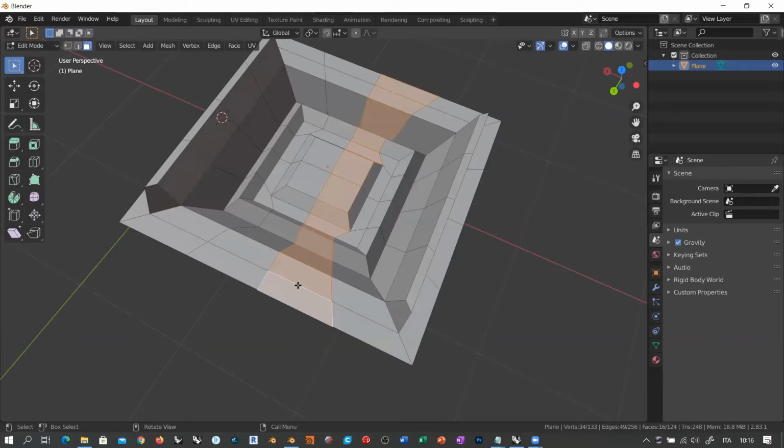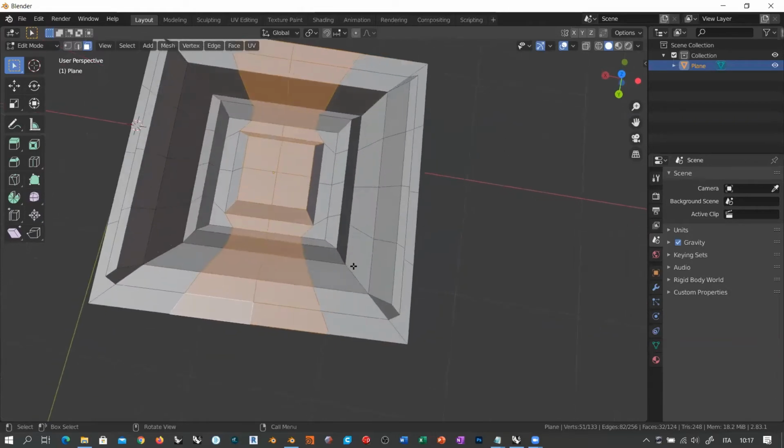Now, what we need is to create defined loops in the U and V directions. So this is, let's say, a V loop. If I Shift Alt click on this edge, I select another loop in this direction. What happens if I Alt click on this edge here? You see that there is this stripe here that flows, passes around this corner, and goes here.